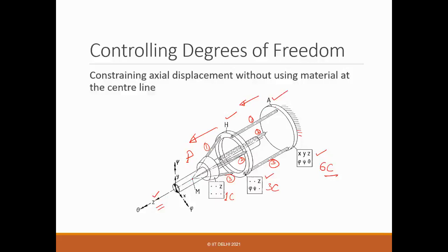So here, from A to H, it's a 3 DOF. H to P, again 3 DOF. So you can say 3 plus 3, 6, right? So all 6 DOF should be there, but that's not true, because the translation is still constrained, just like the two sheet flexure case. So it's still a constraint, and that's why you still have a constraint there.